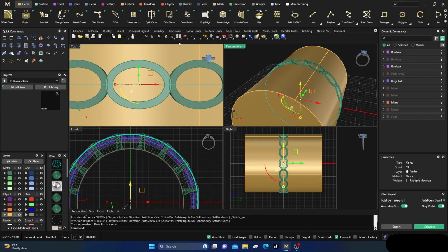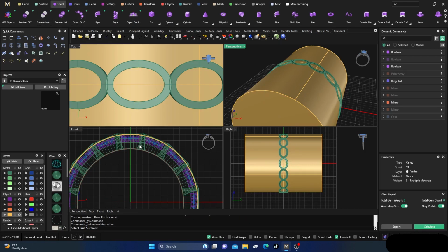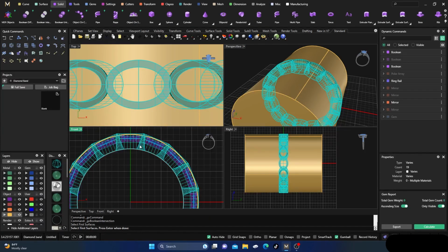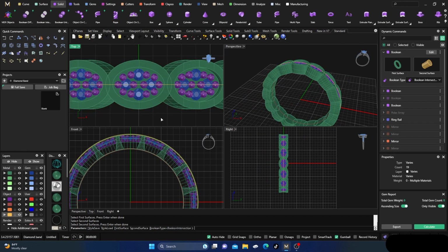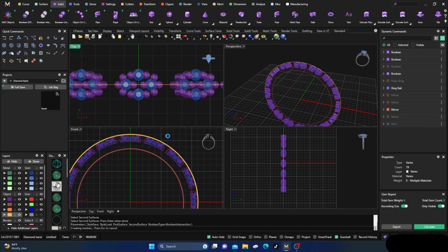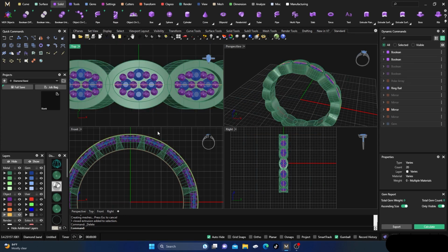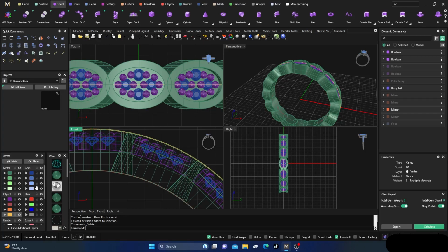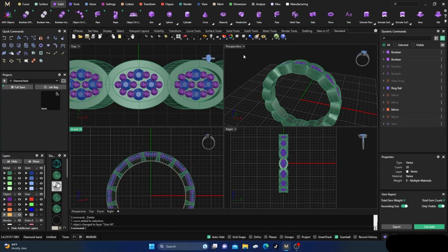All right, and this time we want to go to our solids and do a Boolean intersection. Okay, so the first surface will be our green there, enter, and then our yellow, and then enter. And that should get rid of everything. And then we'll hit enter. And I'll go ahead and grab that yellow surface, just delete it, and grab that yellow curve and kind of hide it. We don't need it anymore. And now we have a rounded surface.